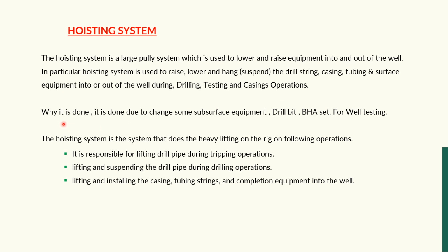So why is it done? It is done due to the need to change some surface equipment. Sometimes some surface equipment needs to be replaced. During the drilling we sometimes have to change the bit to a smaller size, or for some technical reason we need to change to a new bit. Sometimes the BHA set is also changed during the drilling. For well testing, we have to take out all the drill pipe, the drill string, from the wellbore. In this situation, the hoisting system is responsible.